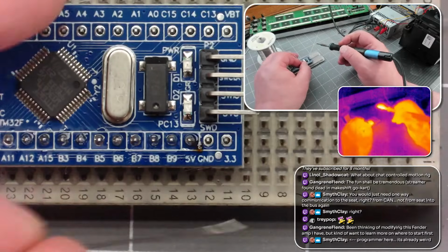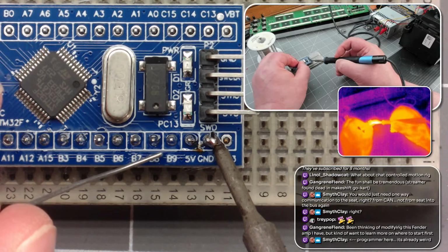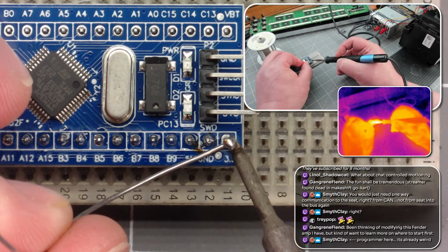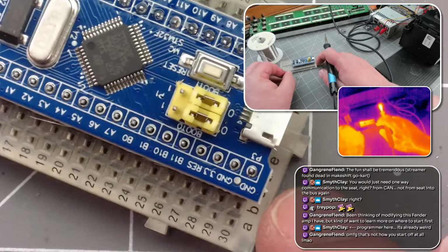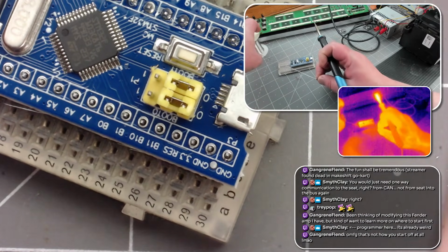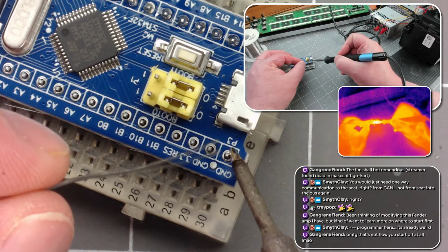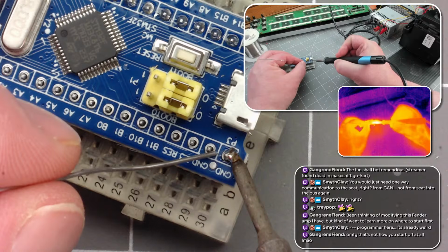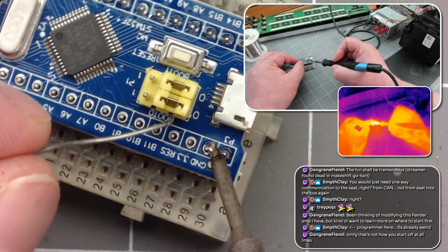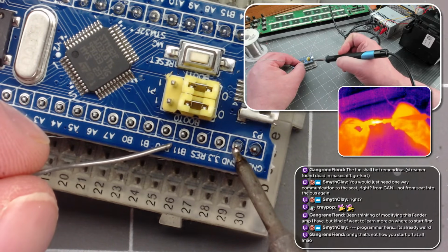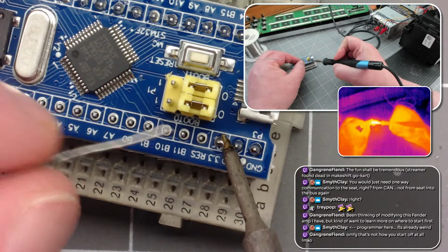And so they have you plugging this into the wall in order to make a 12-volt AC power supply. From there, there's trivial diode and capacitor filtration that will turn it into a 12-volt DC power supply. But it is the world's worst DC power supply because all it has is a couple capacitors and diodes. Now, obviously, wall warts back in the 80s were that kind of crap. But since then, we have all kinds of clever power factor correction and safety. So incredibly stupid to tell a child to plug something into the...